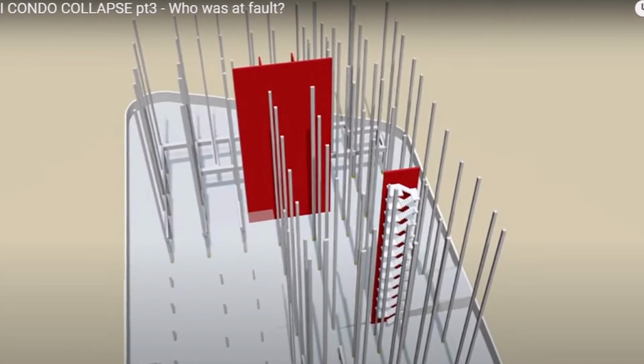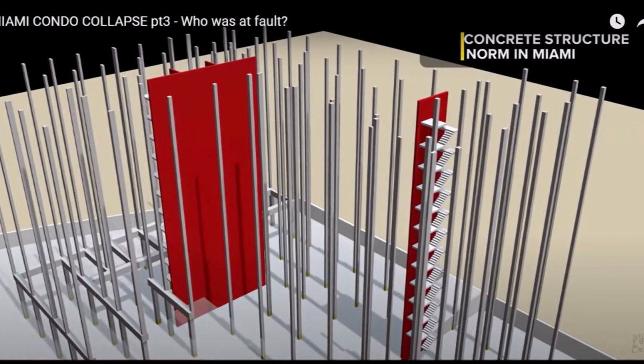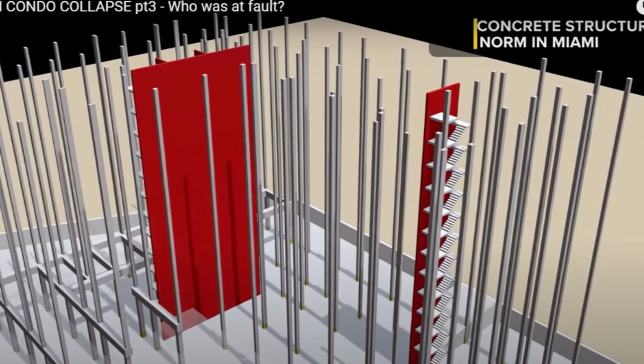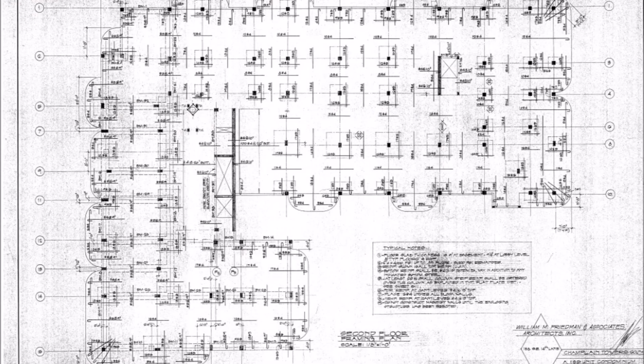And on the west side of the building, the side that did not collapse, they had a lengthy shear wall at the elevator banks. And they had stout columns and transfer beams on the first floor, as you see here. That helps in any shear and moment forces inflicted upon the structure. As you look back at the east side structural drawings, there is no lengthy shear wall, nor are there any transfer beams between the columns, just straight up and down columns to tie to a flat slab.